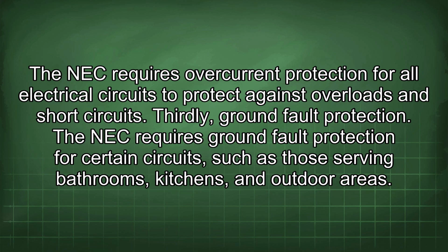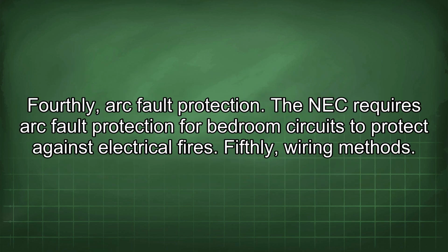Thirdly, ground fault protection. The NEC requires ground fault protection for certain circuits, such as those serving bathrooms, kitchens, and outdoor areas. Fourthly, arc fault protection. The NEC requires arc fault protection for bedroom circuits to protect against electrical fires.